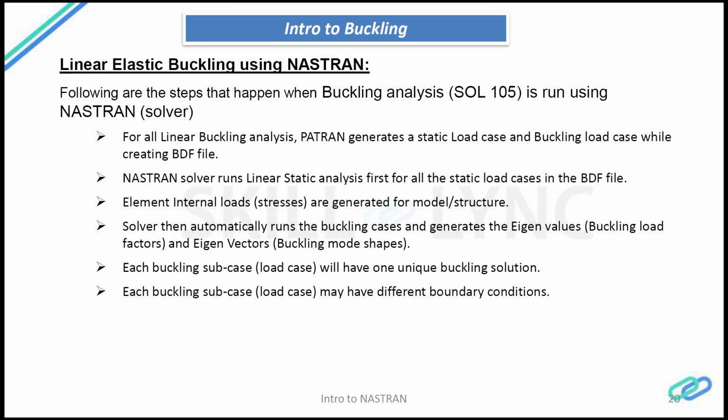And then the Nastran solver runs the static analysis. While carrying out the buckling analysis, Patran generates two types of load cases while writing the deck. One is the static load case, where the structure is treated as a simple static problem, and the reaction forces and element stresses will be computed.